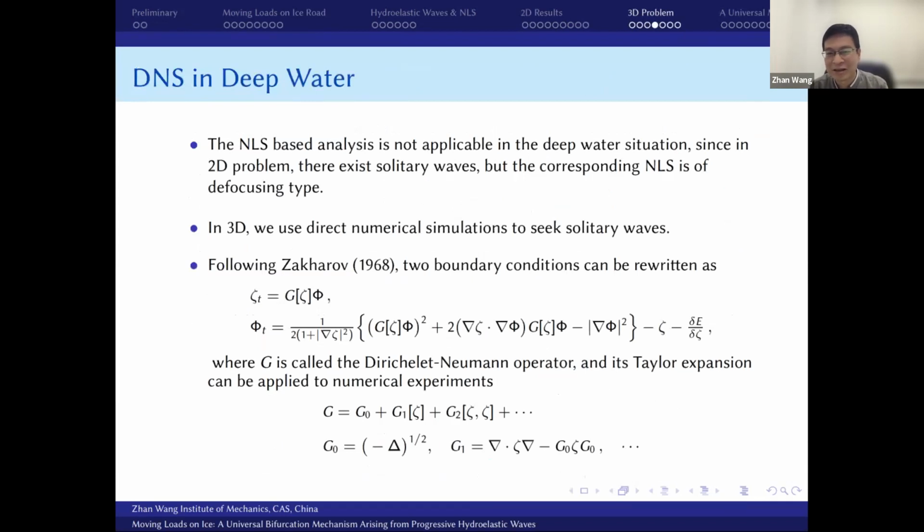If you use the linear Euler-Bernoulli beam with the Laplacian squared, and the amplitude is a bit larger, this numerical scheme cannot capture the results. So I use quite a nonlinear model in this problem. But you can always do that. You can always use the linear elastic model that yesterday Olga showed, and she can compute this for Euler.